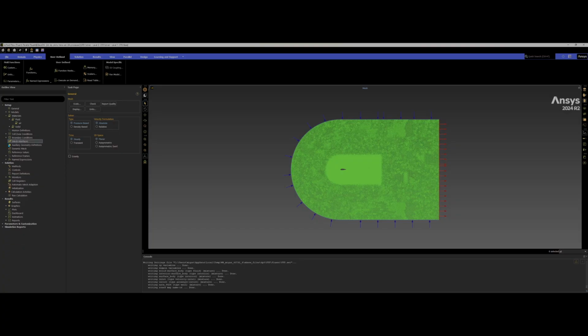And now that that's done, we go to reference values. And then in here, it should be inlet and reference zone, your body. Make sure these values are correct because if they're not, then your coefficients will be way off. All right.